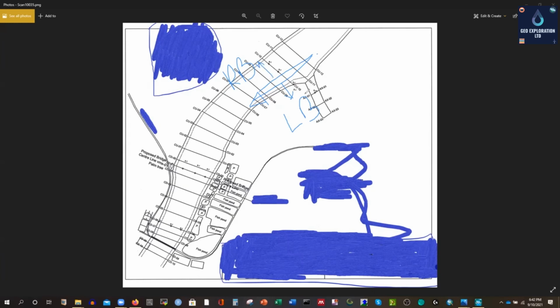But what we need in this plan, we have to survey in such a way that we can measure the cross section from left bank to right bank, because this HEC-RAS model can take the cross sectional values from left bank to right bank, right? So that's what we did here. The survey company just made this plan beforehand, right? They'll take the cross section here, and this interval is 500 meter, half a kilometer. So they made this plan, and then they started their measurement from here.